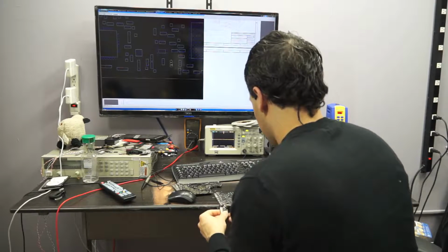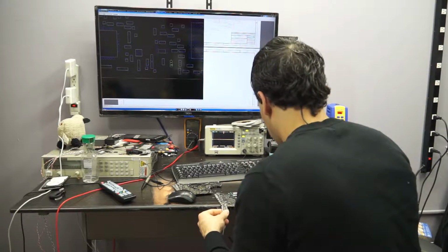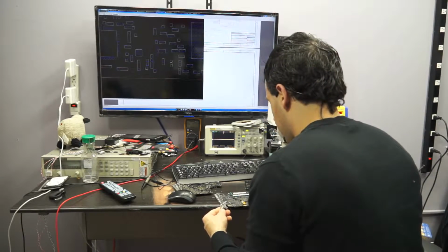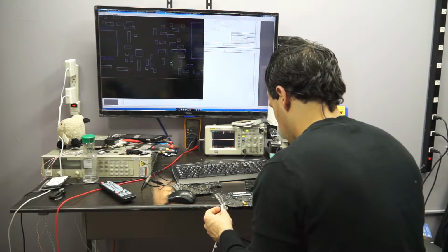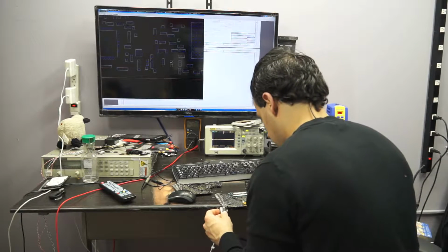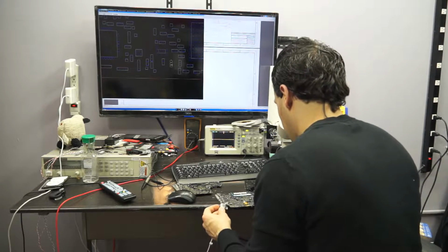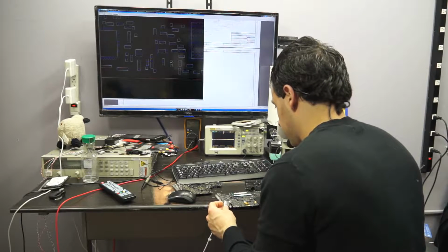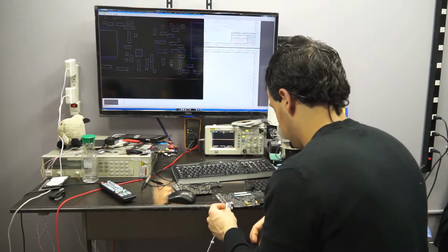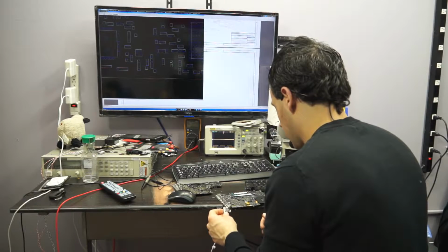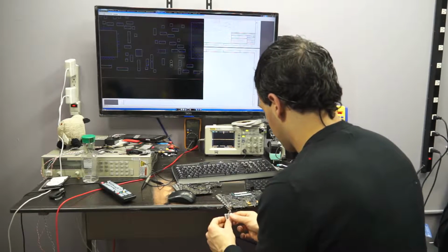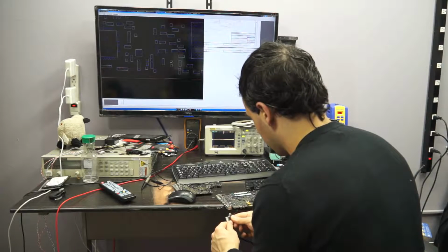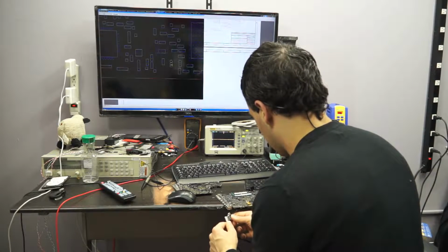So turning this on in SMC bypass mode means I'm going to hold down the power button on the keyboard for a few seconds, and then I'm going to plug the charger in. Unfortunately, when I do that, it still doesn't turn on. Except for now, when it actually did just turn on. Now that it's on in SMC bypass mode, the whole idea is ignoring everything that the SMC is saying to turn on.